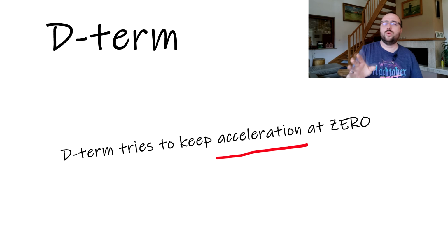Still, we will not be really going into the details of how the D term based on error or acceleration works. That really makes no sense right now. Please do remember that currently the most popular flight controllers, like for example Betaflight and also the ImuFlight, not the INAF by the way, is always computing the D term from the measurement, and then yes, the D term is always acting as a damper.